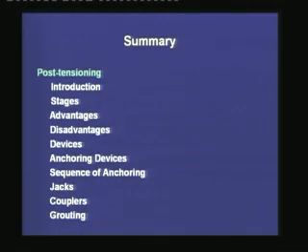Thus, in this lecture, we covered the systems and devices for the post-tensioning operation. Post-tensioning is the type of prestressing where the tendon is tensioned after the hardening of the concrete. The important stages of post-tensioning are: first, the concrete is cast with a duct inside it.